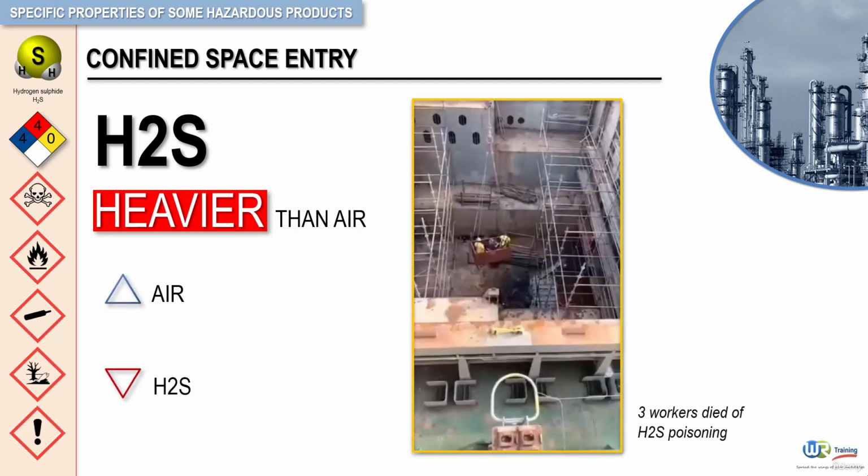The following video is taken from a construction site and shows a hydrogen sulfide multiple fatalities incident. Now, before viewing the video, it is important to note that 3 workers rushed to the scene when they were summoned to rescue 2 other workers who had fallen unconscious due to hydrogen sulfide inhalation. One of the would-be rescuers had not worn the proper breathing apparatus and also collapsed. Despite attempts at resuscitation, the 3 workers died.